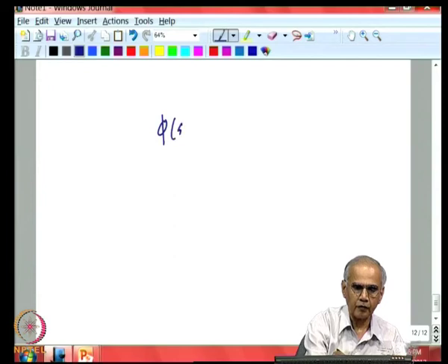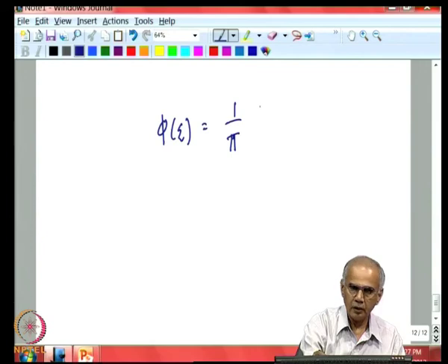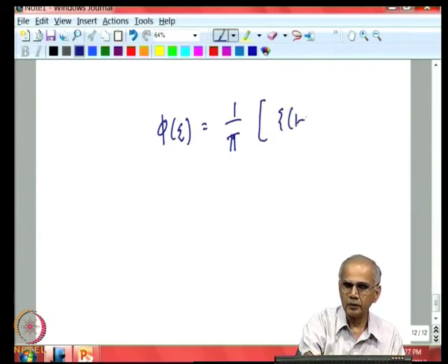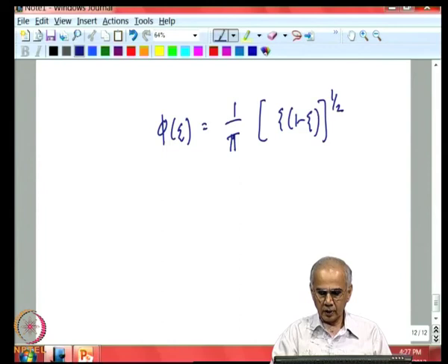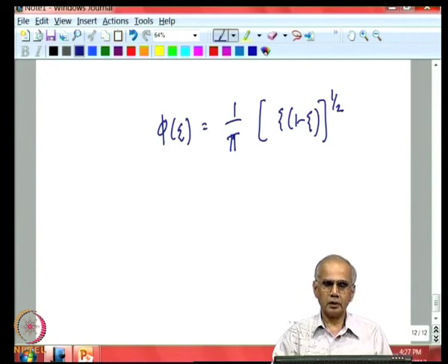The non-dimensional temperature profile will come out as 1 over pi times psi into (1 minus psi) under a square root. So, this is an unusual, very rare result, wherein you get an analytical solution to the temperature profile in a gas having a vibration-rotation band in the limit where the path length is very large,